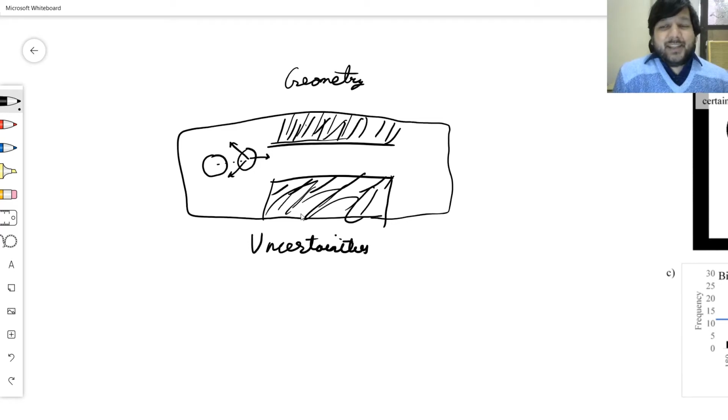In the case of potential field, depending upon the location, it will cause some minor repulsion. The robot is not going to be very bothered about it until it gets very close to the obstacle. And once it gets very close to the obstacle, then the false positive is a rarity. Geometry can completely mess up if I am not sure whether something is an obstacle or not. It's not just a term which gets added to a straight mathematical formula. It's more than that. It decides where I enter, where I don't enter. The obstacles have a geometric meaning.